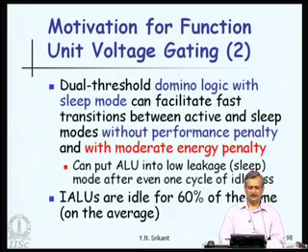But the nice thing about these dual threshold domino logic circuits is they can actually switch between these active and sleep states with very little performance penalty and very moderate energy penalty. So, observe the words, there is not much performance penalty, because we are going to switch within one cycle. So, active to low is one cycle, low to active is another cycle, but if the switching is very frequent, energy consumption becomes high. So, there is moderate energy penalty for such switching.